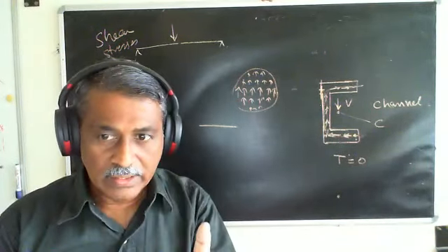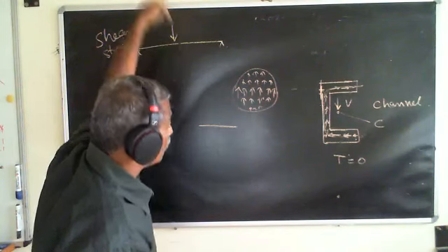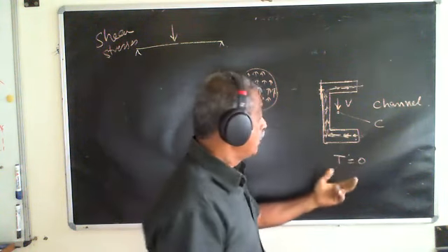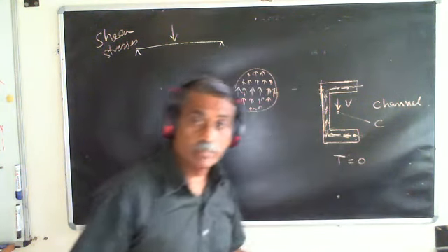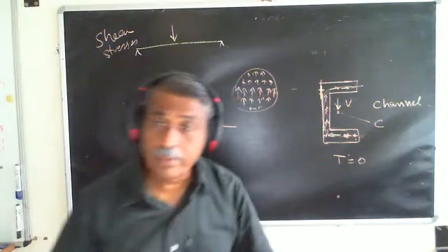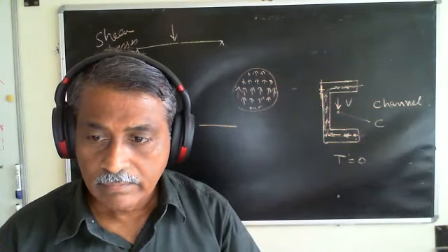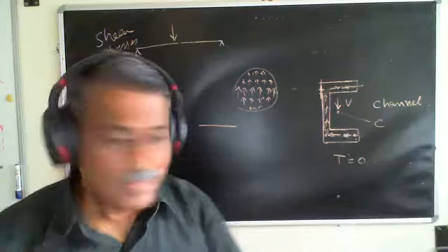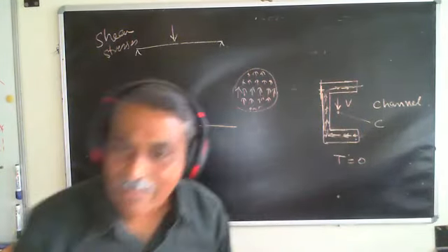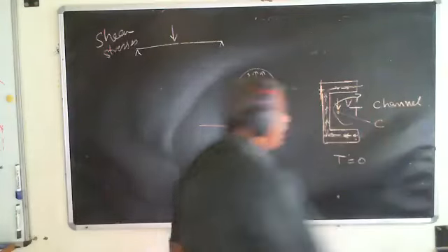This is an important thing that I want you to get. I have a beam and I am applying a transverse load, right? If the transverse load is applied through this centroid, I'm trying to find out if it will produce any torque at all or not. Will it produce torque? If I apply like this, will it produce torque? Any guesses? Think about it. If I take moment about this, for this, this and this, all are in the same direction. They go only like this, right? Which means that I produce a torque T,